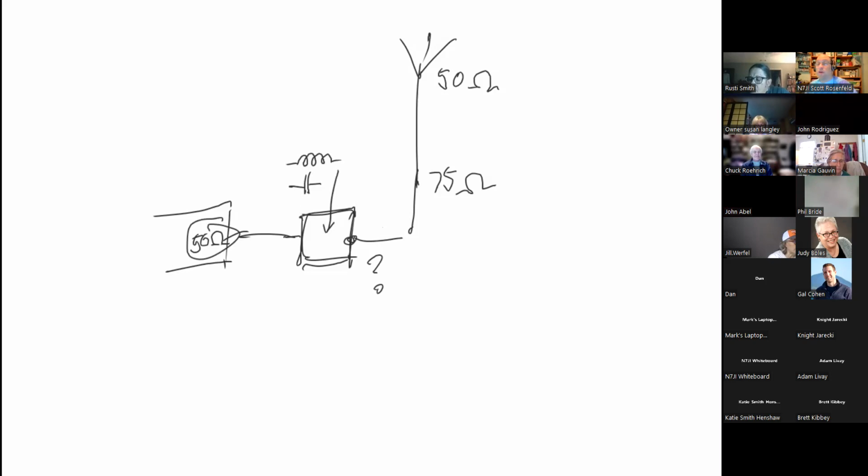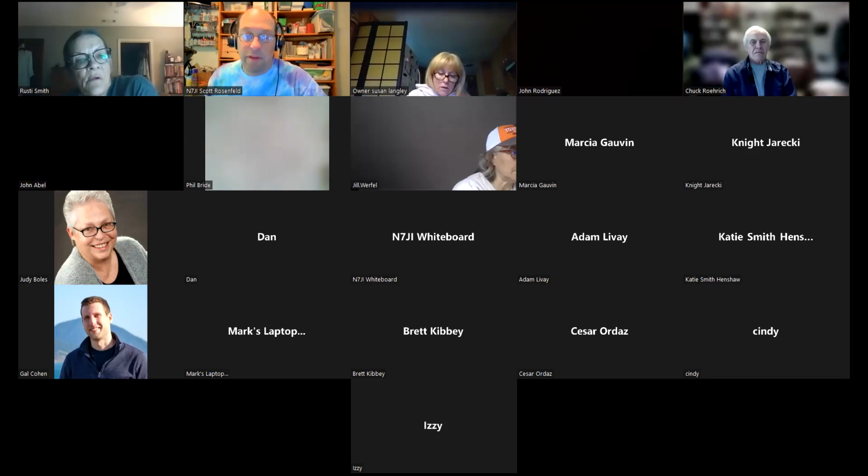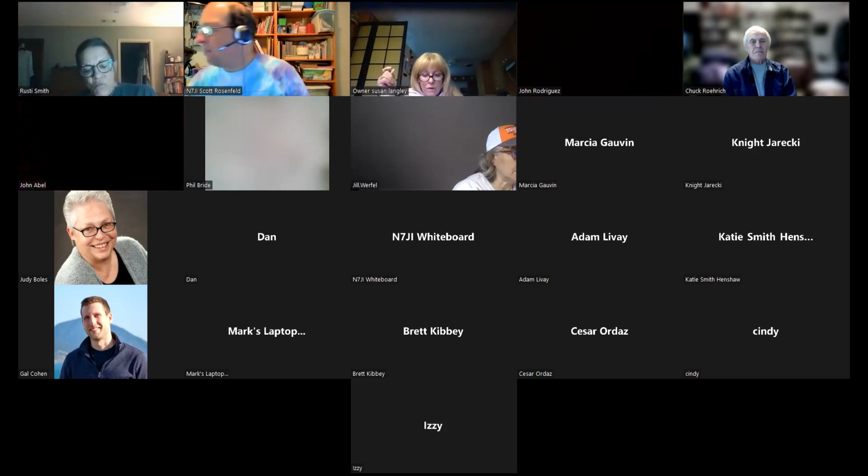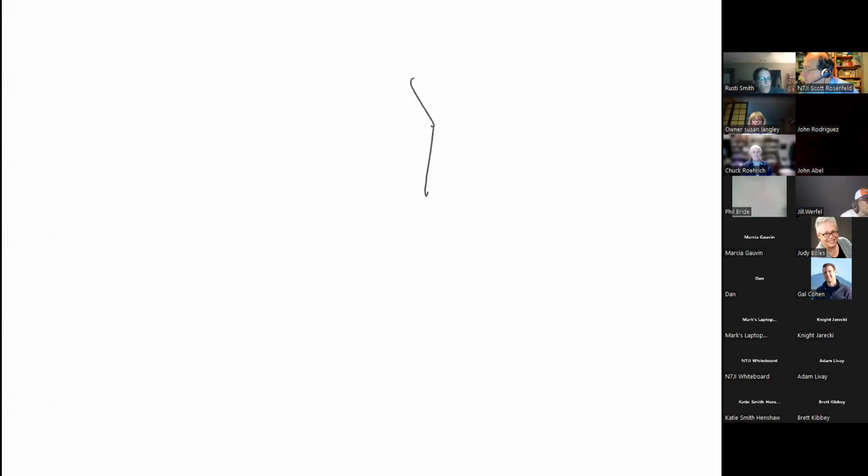It's essentially a tuned circuit that allows us to modify what the impedance looks like. And that's known as impedance matching. Is the impedance that's coming into the thing that fixes it, was that 50 plus 75? It is not. Now that's another important thing. That's a very good distinction, because if I have an impedance, let's say this is 50 ohms, and we're actually going to do feed lines next. A feed line has something called a characteristic impedance.